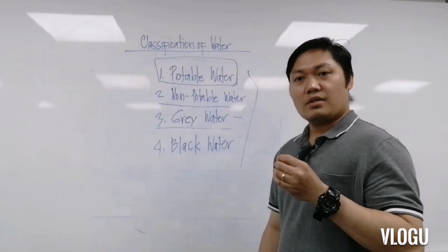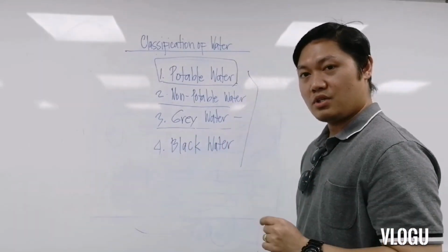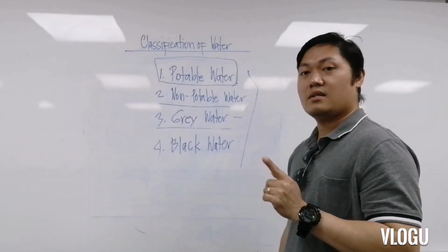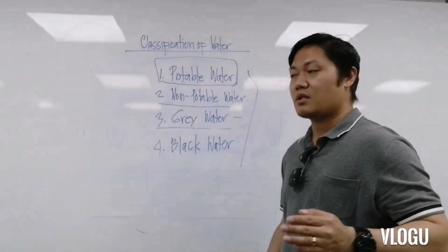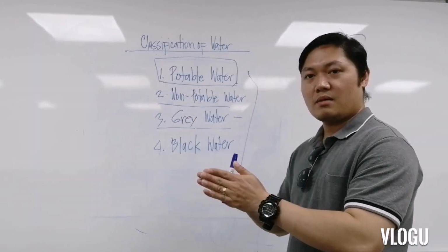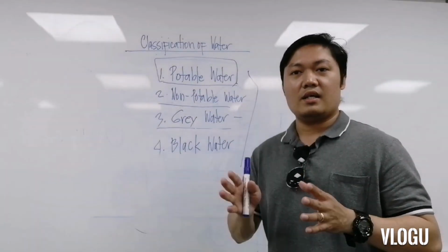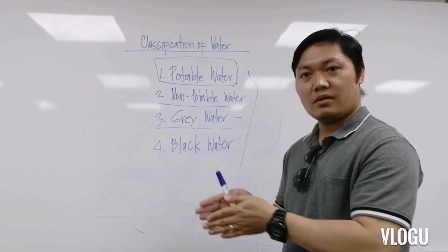The main thing to emphasize first is the survey setting out. You are going to establish points in order to determine the limit of your work, and at the same time the limit of your excavation.